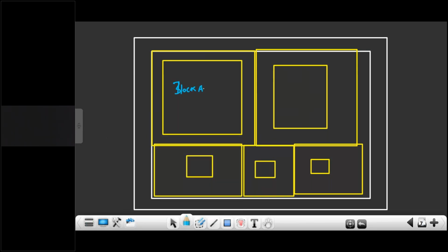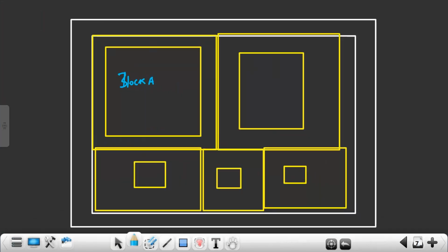Each block owner will start doing physical design on each block. After doing physical design, all the blocks are integrated, tested for final sign off, and sent to the foundry. Create GDS and send to the foundry. So now we are doing the physical design of each block. This is block B. Each engineer is responsible for doing physical design of their block.